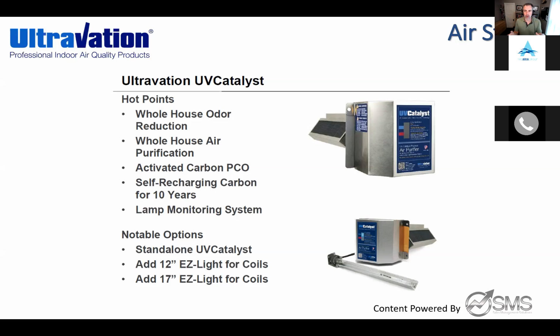That's the whole point of putting UV over a surface: as long as UVC wavelength light is shining over that coil surface at 12 inches or less, it's inhibiting the growth from ever happening. That's another reason why we explain to people, even if you're not running your system, these must stay powered 24/7. If you shut a UVC bulb off, then you've just stopped its inhibiting factor.